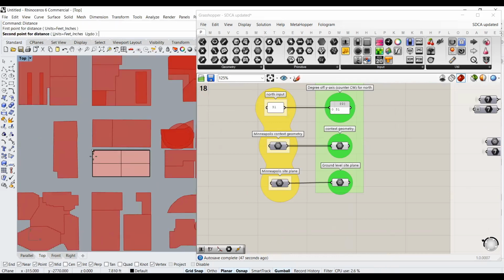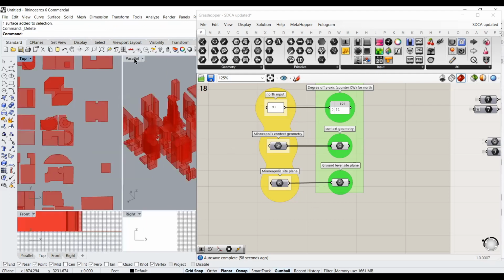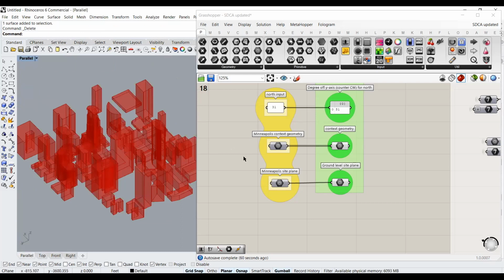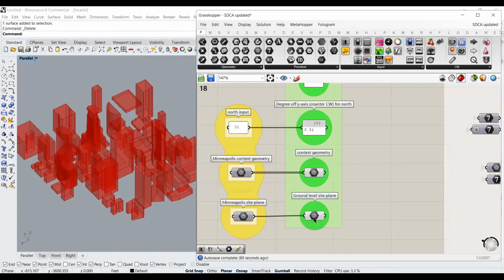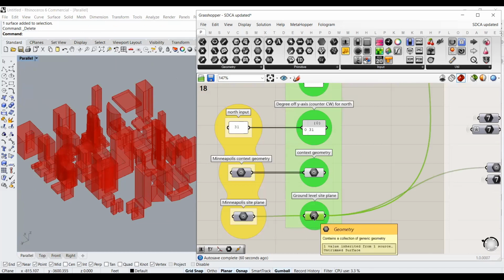So yeah, 320 by 150. So just keep that in mind. That's another reason why 10 feet is a good grid size. But if you were to use like 12 or something, just make sure that the dimensions of that plane are divisible by it without any remainders.